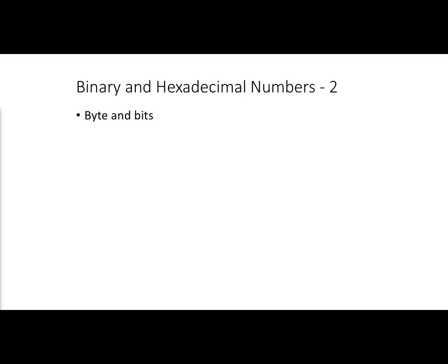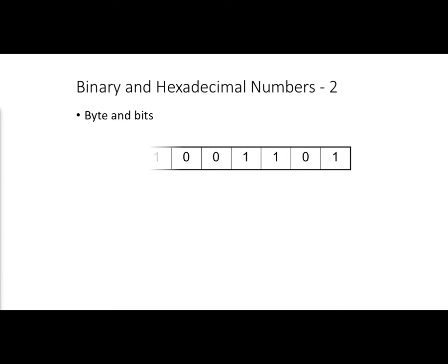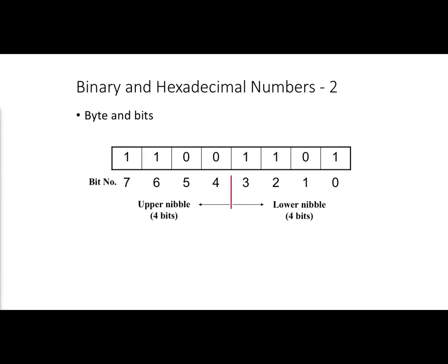Typically, if you've had your Digital Design 1 class in recent memory, you remember how to convert from binary to hexadecimal. You divide things into 2 nibbles, the lower and upper nibble, and then you assign letters or numbers to the 4-bit grouping.